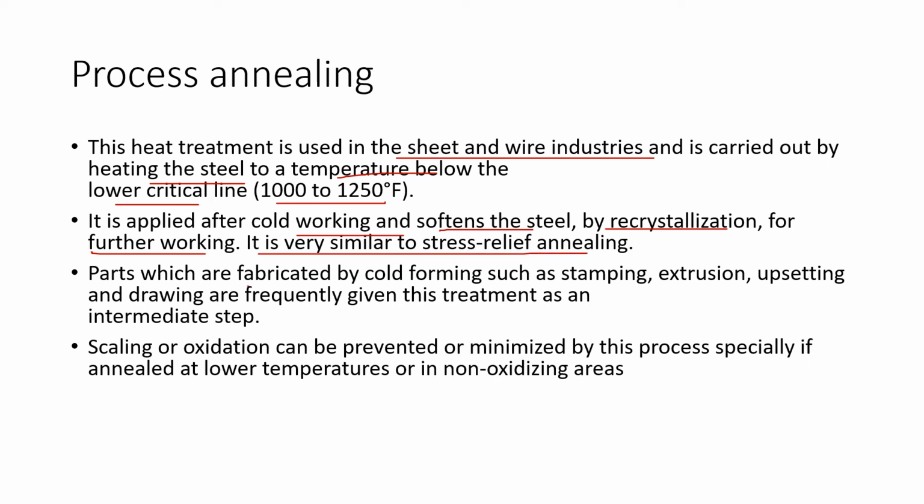Parts which are fabricated by cold forming, such as stamping, extrusion, offsetting, drawing, are frequently given this treatment as an intermediate step. Scaling or oxidation can be prevented or minimized by this process, especially if annealed at lower temperature or in non-oxidizing atmospheres.